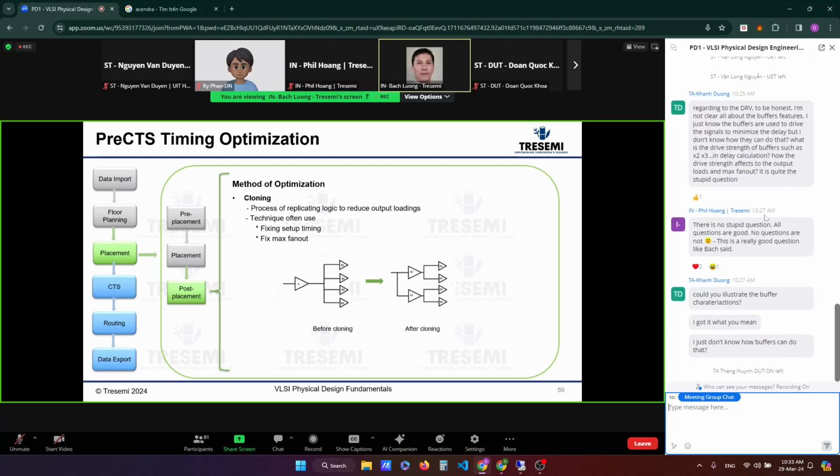Yes, the characterization data is done by the cell library team. There is a separate library team that builds the library and characterizes it. They have these curves and things like that to show you exactly how the different drive strengths tolerate the fanout and the cap.